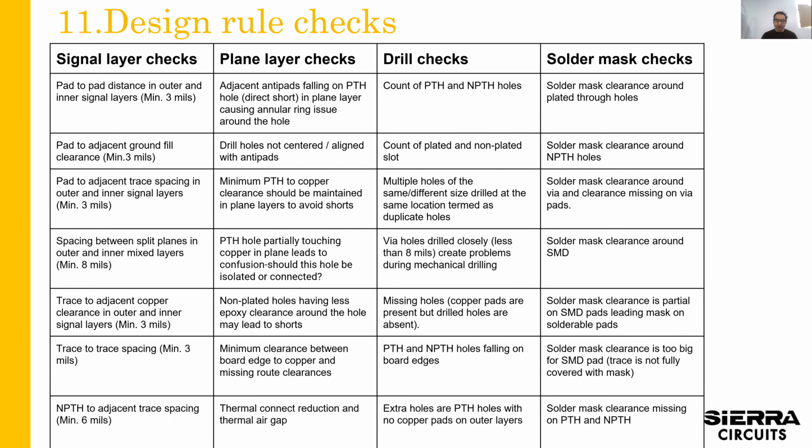The reason it's a little hard to check for is because of the way we build boards. You first have to enlarge your vias, then run your drill to copper check, because that's the size of the drill we're going to be drilling. And when you send us your designs, it's really a finished drill size. So that's why it sometimes gets missed, which is okay. That's why we're here, and that's why we do our checks.